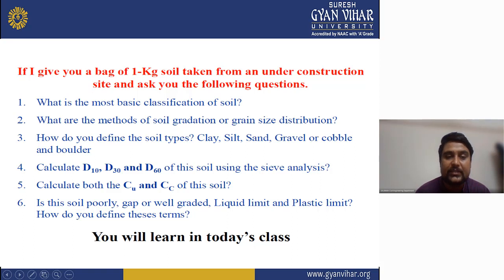These are the significance of GSD, meaning grain size distribution. Now we will see how to determine the grain size distribution, how we perform this test. In coarse-grained soil, by sieve analysis; in fine-grained soil, by hydrometer analysis. As you can see, if the soil is coarse-grained, then we have to do sieve analysis. If the soil grain is fine, we have to do hydrometer analysis.